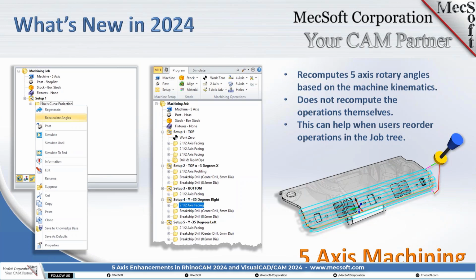So imagine this: if you're machining something and then you retract from the last toolpath position on an operation, in 5-axis mode, the angles of the machine tool will be in a certain configuration. And then if you want to start the next operation, the next operation needs to understand where the machine tool angles were set at the end of the previous operation. If this is not done correctly, then you might have some random transfer moves going from the previous operation to the next operation.